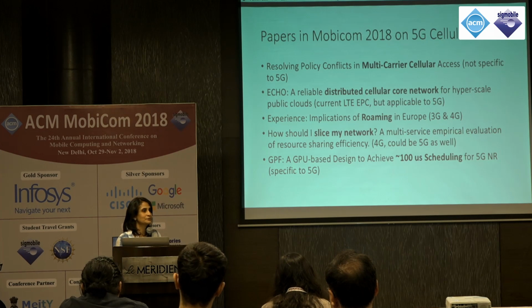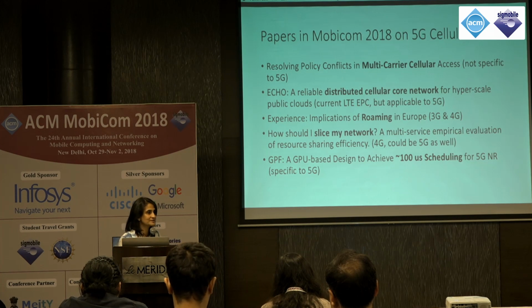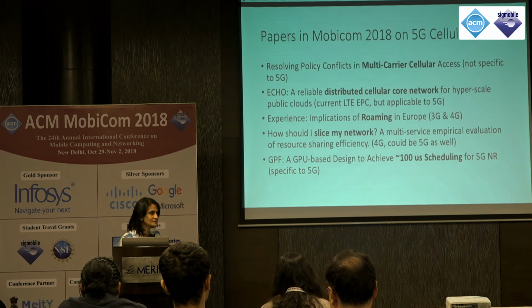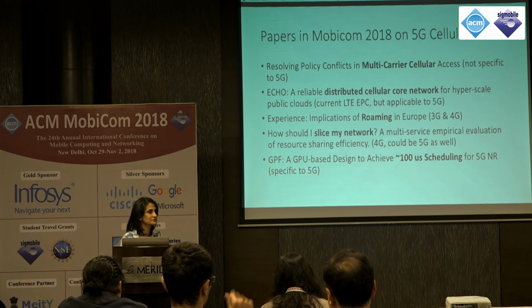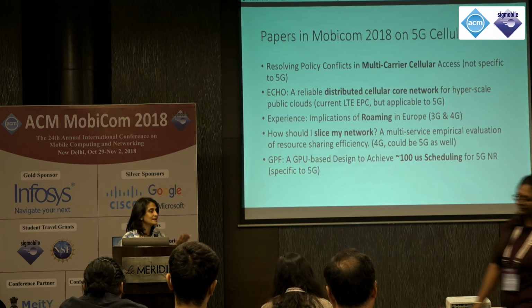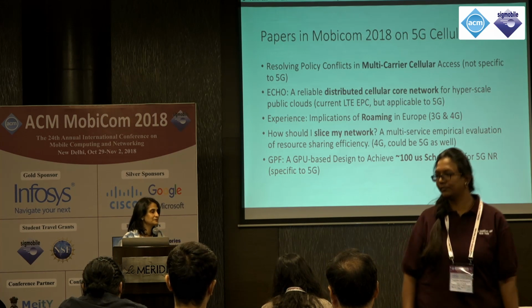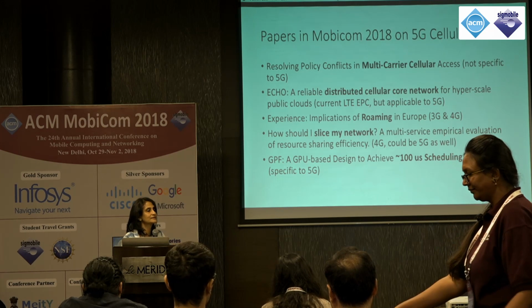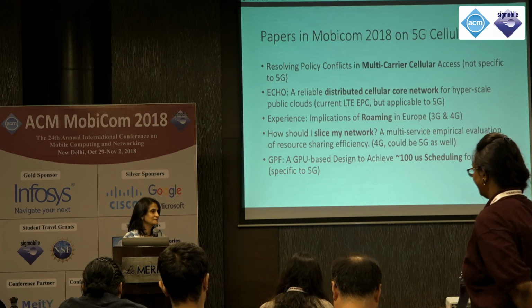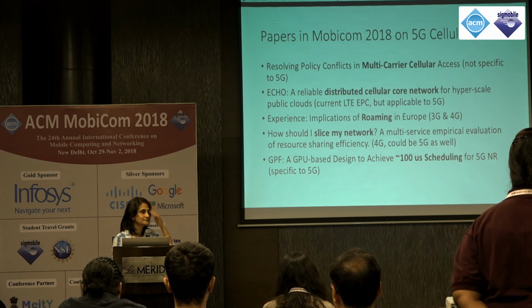So you have to get new handsets, new base stations, new infrastructure. But your handset can fall back to UMTS if the 5G network is not available, much as we do today, right? You fall back from 4G to 3G. So in that sense, yes, it's backward compatible, but inherently the architecture, the system is not backward compatible.